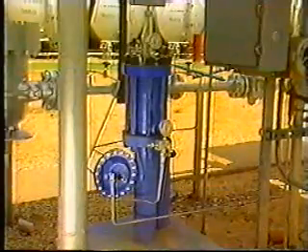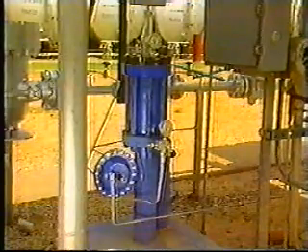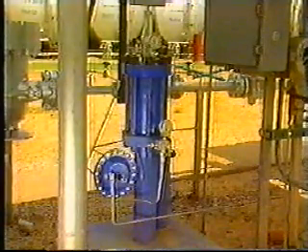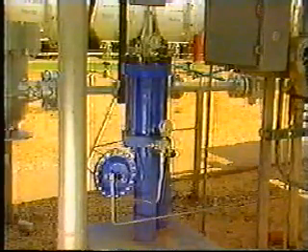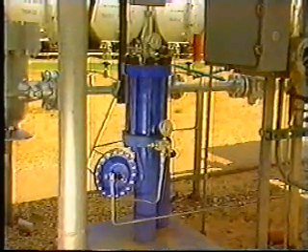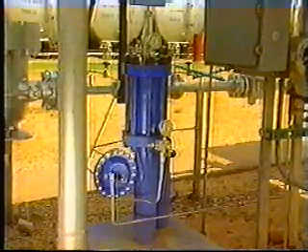Component measurement relies on sampling of the NGL stream. This sampling assures the quality or composition of the product stream. Usually this sampling is done with a continuous sampler. For a more detailed explanation of the sampling methods used, review the information covering NGL sampling in the module Natural Gas and NGL Sampling.